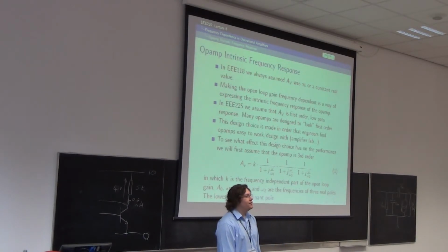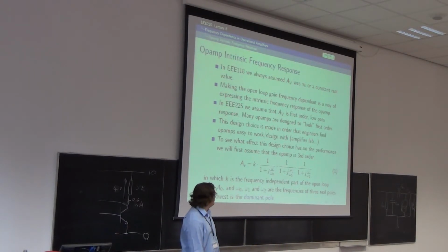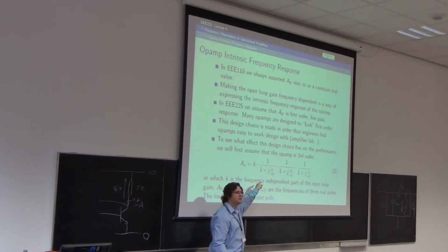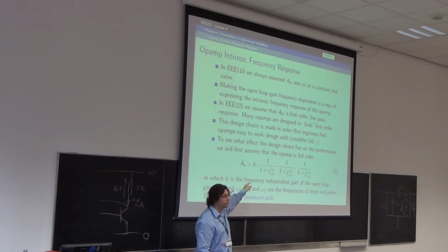Right, okay. If you've got real poles, that is to say, if you multiplied all this stuff out and could still factorise the denominator and get real factors, that's to say not complex factors, I couldn't have resonance because my poles are real.